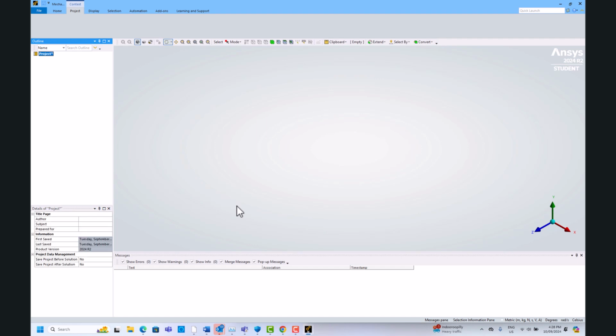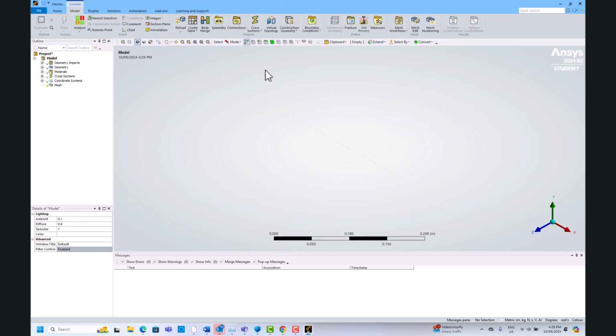But just in general, if you're doing an FEA, mesh is probably one of the most important things to deal with, because generally, the finer the mesh you have, the better accuracy you're going to have, as well as a longer computational time you're going to have to deal with. So you have to find an optimum mesh or a good enough mesh to give you good enough accuracy and reasonable calculation time. But in our case, we don't need to worry about that.